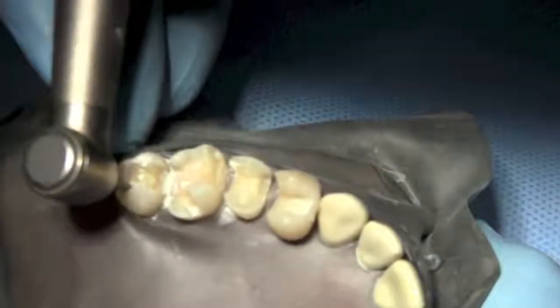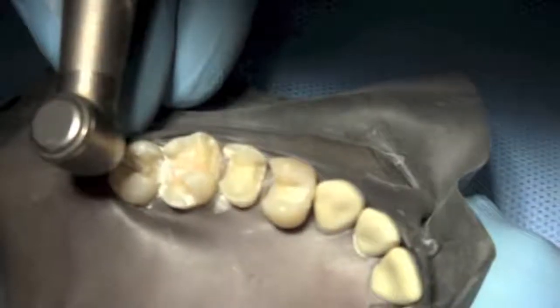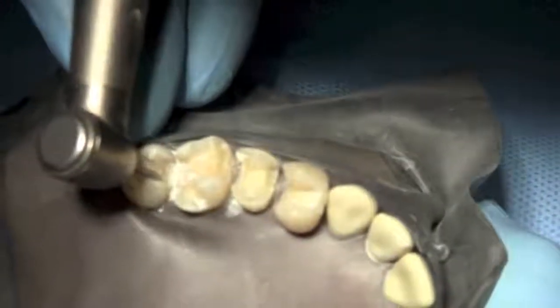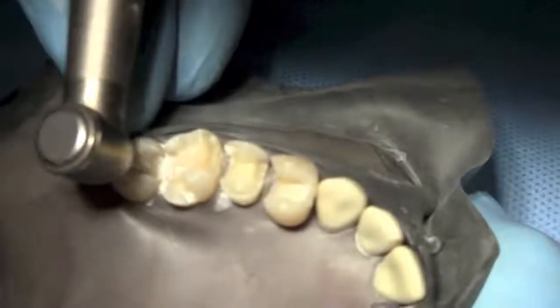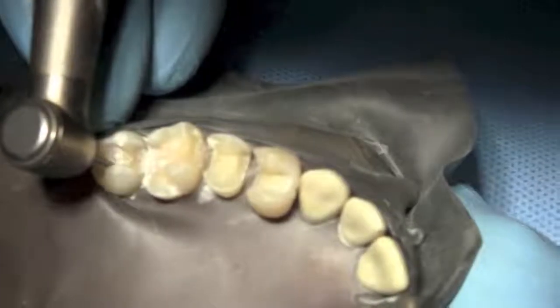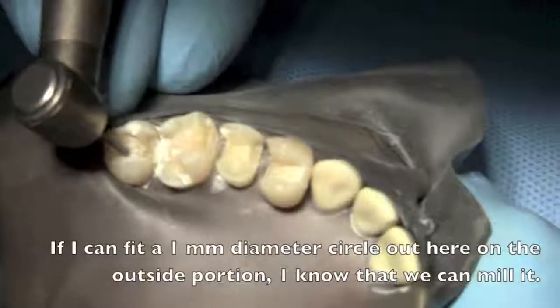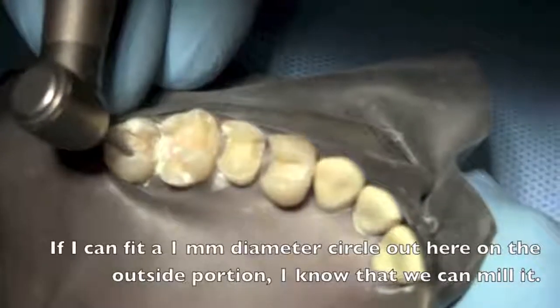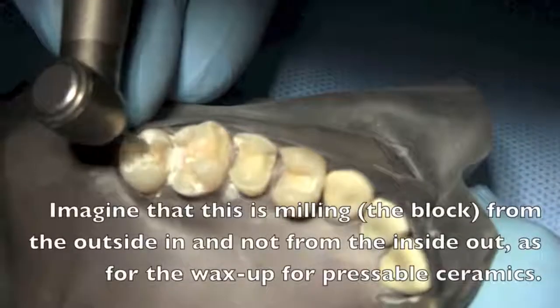People say that the preparations for milled ceramics are so much more aggressive. I disagree. It's just a very subtle rounding of these little transitions that makes all the difference in the world. Right there. Now we know we can mill that, because if I can fit a 1 millimeter circle out here on the outside portion, I know that we can mill it, because remember, we have to imagine this is milling from the outside in, not from the inside out.